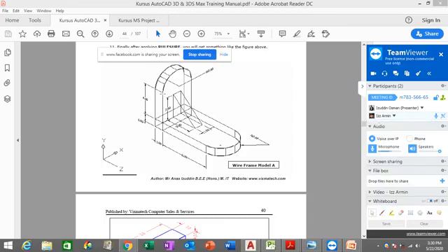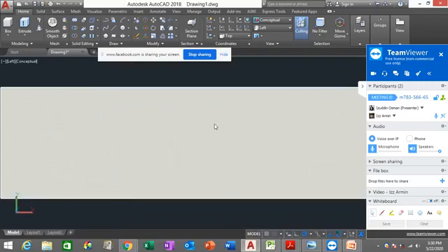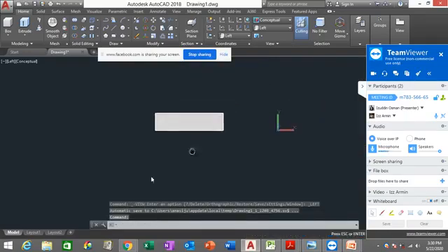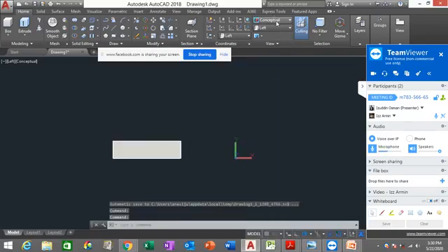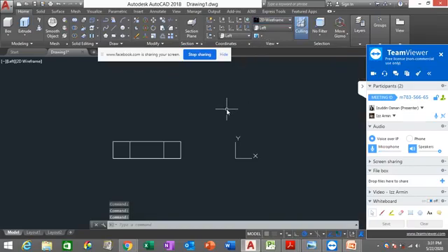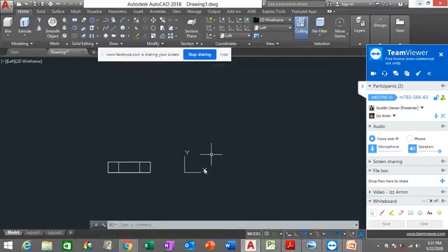So I'm trying to draw this side view of this part, which is on the left view of this object. So I'm going to change this to left view first. All right, left. So I'm going to scroll down a little bit to zoom out. All right. And I'm going to change back to 2D wireframe. Because I'm going to draw this part first, which is the height is 5, right? The height is 5.